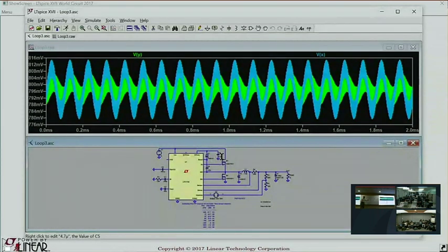Now the thing is, this is not a linear circuit. This switch is fully on or fully off. They don't just mix frequencies, they mix frequencies as much as possible. And that's not even the worst of it. The worst of it is that flip-flop. There's absolutely no frequency domain description for flip-flop. So there is no frequency domain description of this circuit. There just isn't.